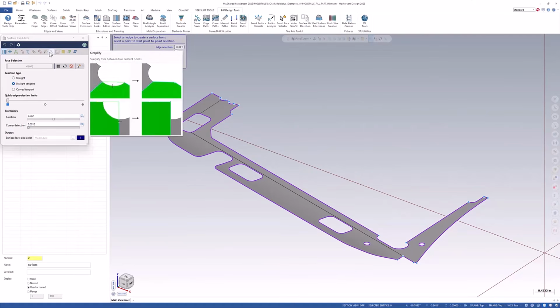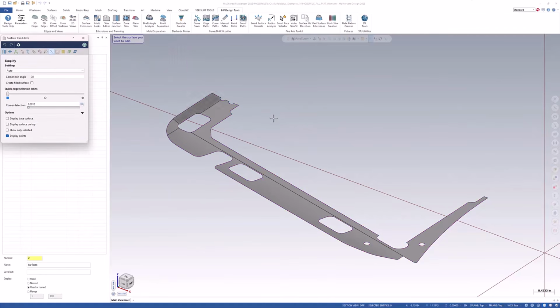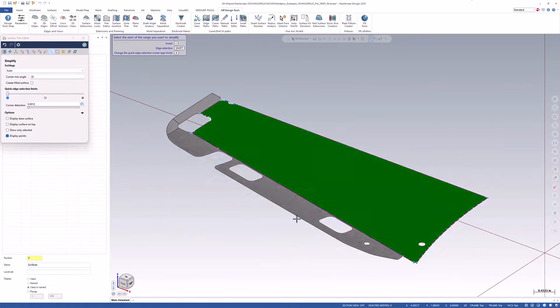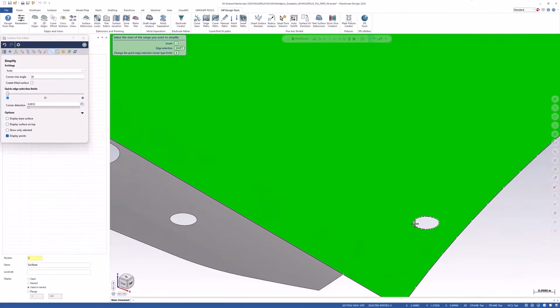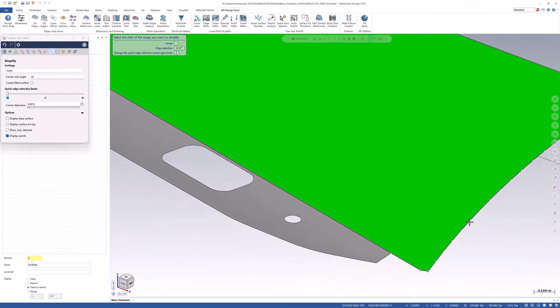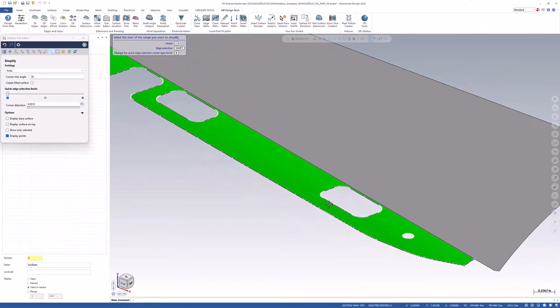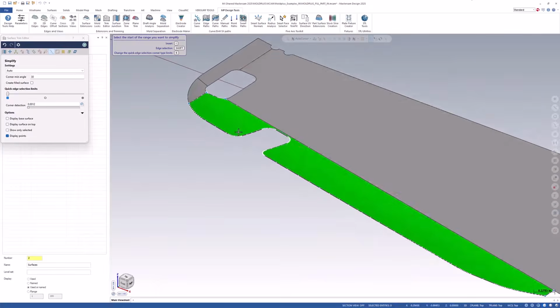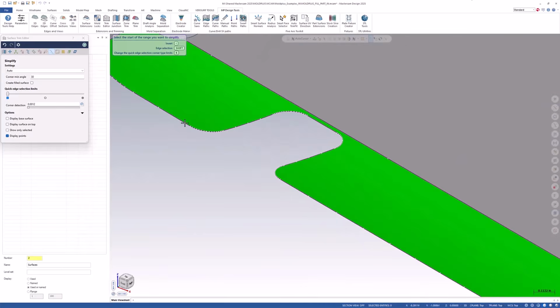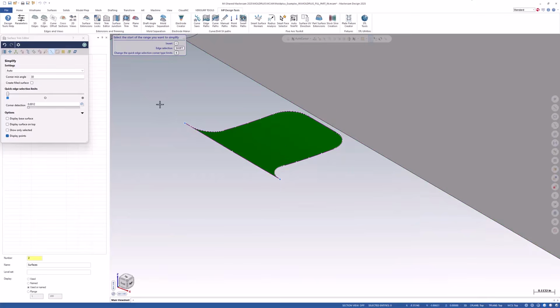using this simplify tool here. So there's a bunch of little toolbars there. Fill in from here to here. There you go. All right, and once we're here, you can simply right click, say boom, remove holes. Done. It's gone. Same thing here. Click on this. We'll remove these holes. All gone. Fill this in with just a couple clicks from there to there.